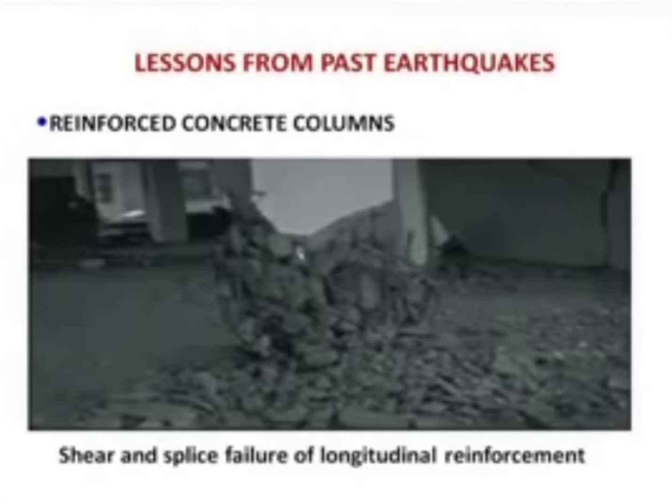You can't see here, but you know that when you are constructing the pile cap or even the shallow footing, you are taking the reinforcement from the foundation level and you are reaching to the ground level or slightly above the ground level, and then you lap your reinforcement, means another piece of reinforcement is lapped with this old reinforcement.